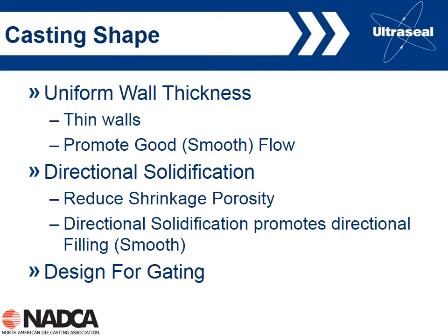So in the long run, maybe you're going to get lower porosity, lower scrap, and lower costs. So machining the hole might make it more expensive up front, but by running a lower scrap rate, then your overall cost can potentially be lower. So something to think about.